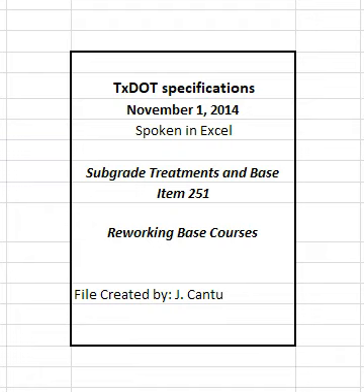Mixing, spreading, blading, shaping, compacting, and finishing new or existing base material will not be paid for directly but will be subsidiary to this item. Sprinkling and rolling, except proof rolling, will not be paid for directly but will be subsidiary to this item, unless otherwise shown on the plans. When proof rolling is shown on the plans or directed by the engineer, it will be paid for in accordance with Item 216, Proof Rolling.